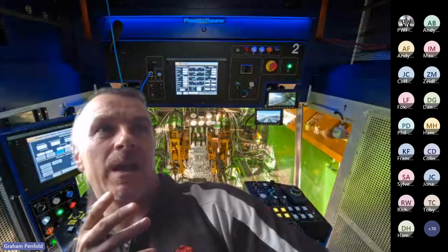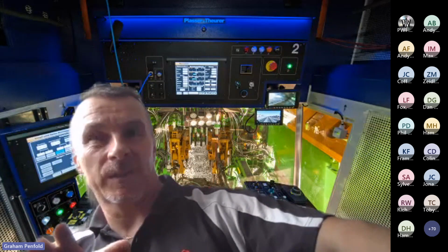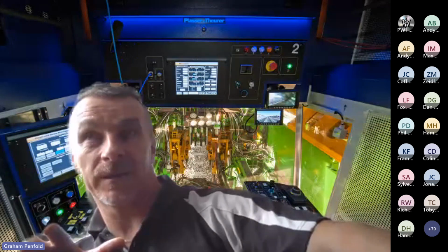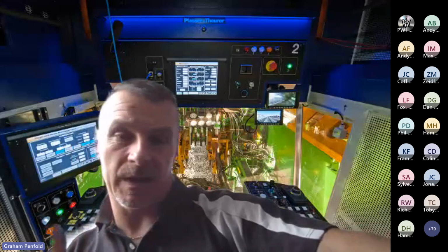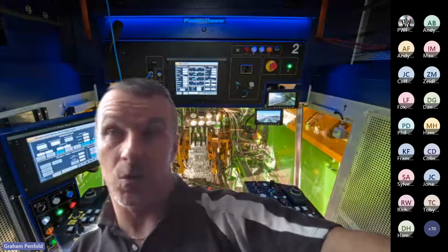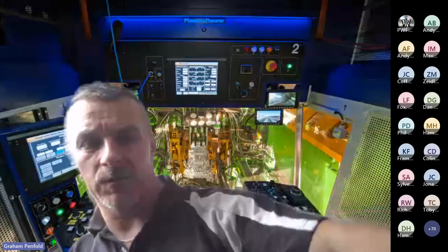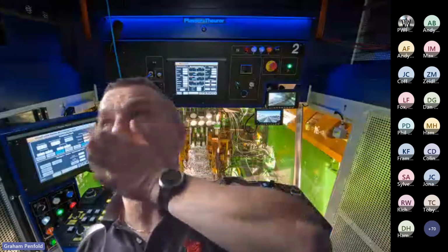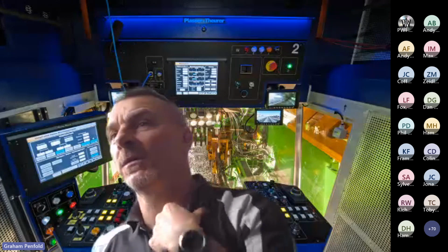Overlift again, it's the benefits of both what I was saying. You get the benefits of the longevity and your track position, because if we overlift and DTS, like I was saying, not only are we getting the good compaction on maybe a ballast cleaning site or a renewal site, if we overlift it after settlement, we are closer to our design positions. It's a really good point, because what I've said in those last few slides is probably more pertinent to renewals than it is maintenance.